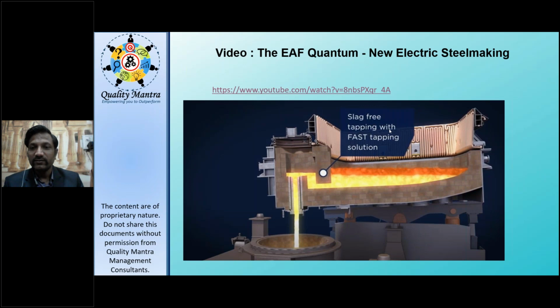Okay, so this is about the electric arc furnace. Now you have the molten metal from the blast furnace and the molten metal from the electric arc furnace, and the next step will be to refine it further if required. Electric arc furnace means if everything has been as per the chemistry, you don't need to do it again, but almost always it is required. So the next thing will be ladle refining, or there are processes like degassing also, vacuum degassing. That we will learn in Monday's session.